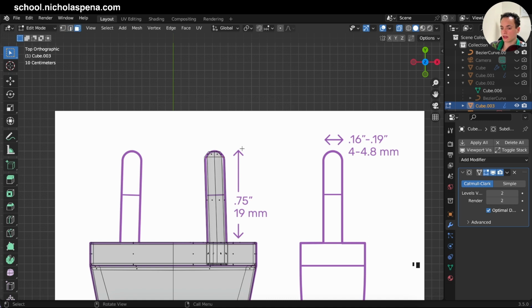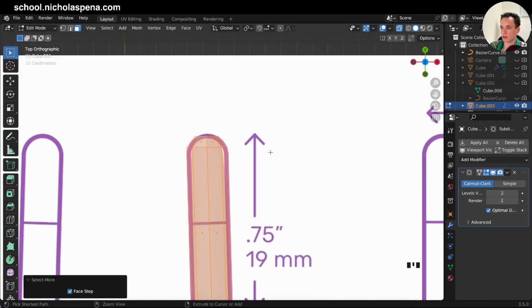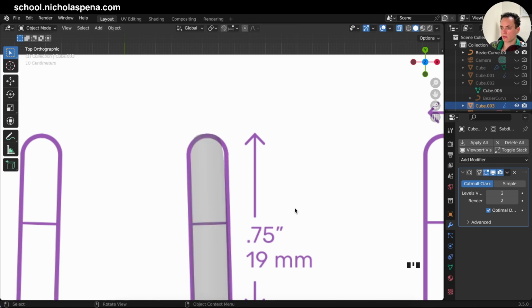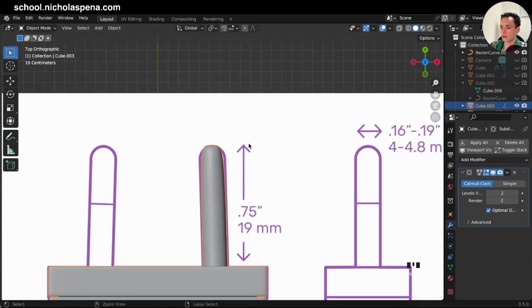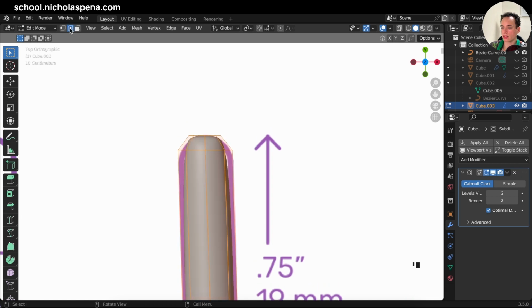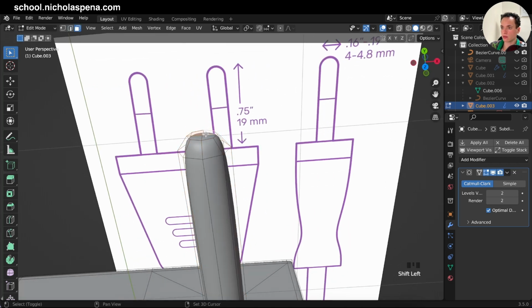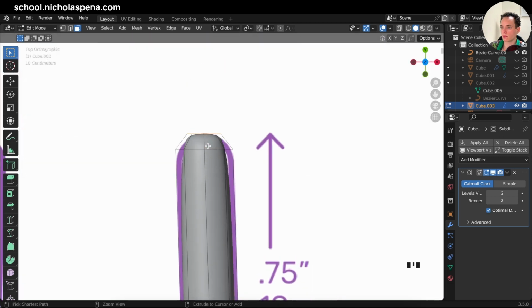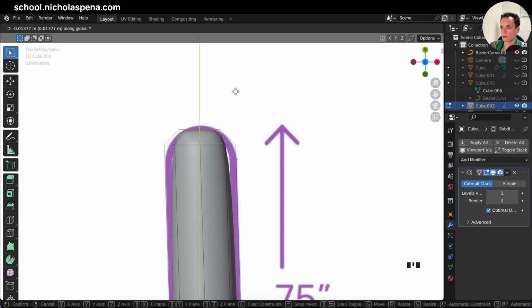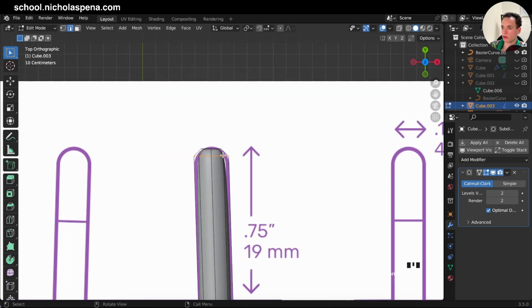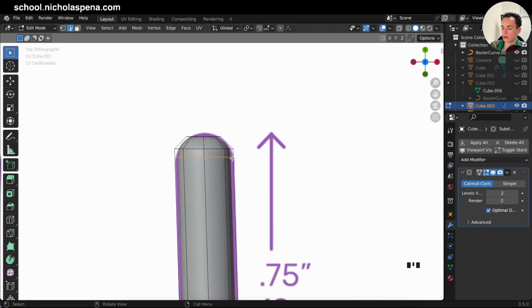and faces select, Control, just select one face and Control plus to select everything. I'm going to put this a little bigger, S, like this. Then face select, I can bring this down. Put another loop cut to support this here. Control R, click, bring this up like this.